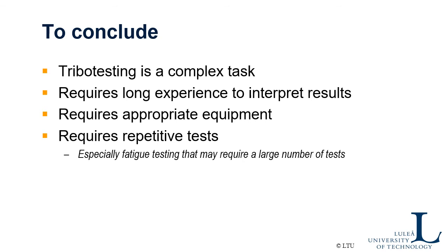You should also do many tests, because they are not very accurate tests, and there are many stochastic phenomena taking place, especially when you have fatigue. When you do fatigue testing, then you really need to do, say, 30 tests of the same in order to learn how the statistics give you a distribution of the service life, for example.